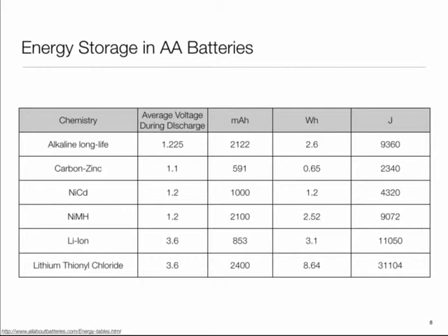I mean, the fact that lithium ion has 3.6 versus these guys have 1.2, would that affect any aspect of your system design? One lithium battery instead of like three in a series, right? So it affects the size of your design, the volume of the packaging that you have. So those things end up making a difference also.